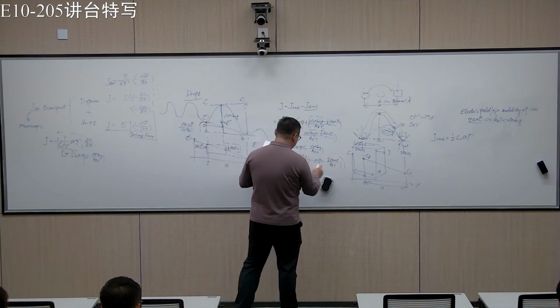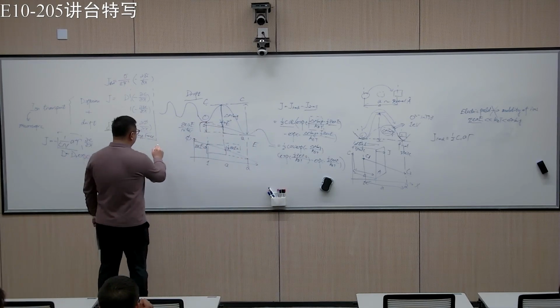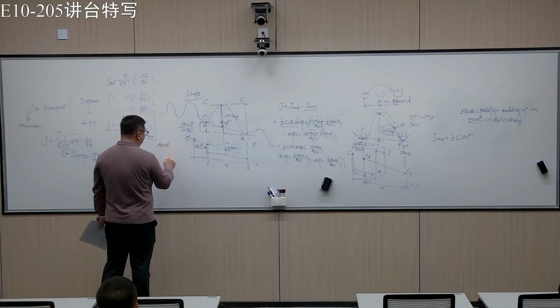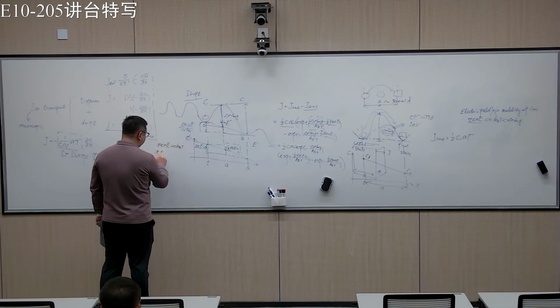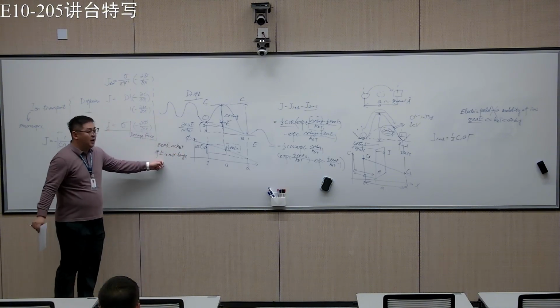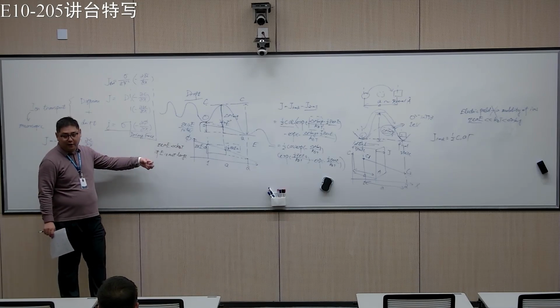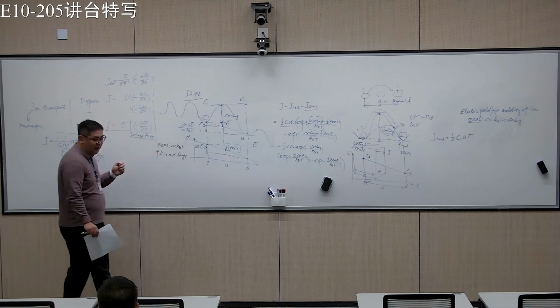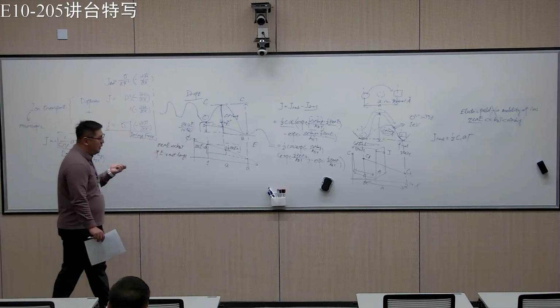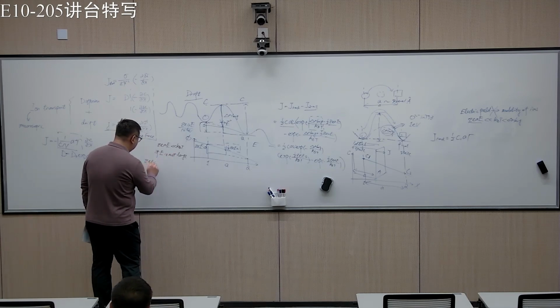We already said that the delta E is much smaller than kBT if E is not very large. Only in very extreme cases, like thin films or at the interfaces, do you have a very large electric field. Otherwise the electric field won't be very large, so the EA over kBT is much smaller than 1.